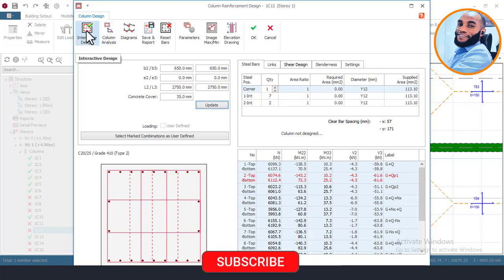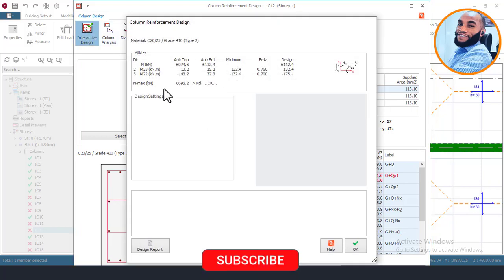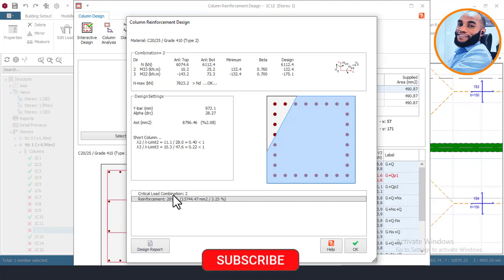And I'm now clicking on interactive design here, and I'll wait for the column to design again. Once you're able to see your column, if it's perfectly okay, you will not see any warning in here. What you will see is the reinforcement. So once you're able to see the size of the reinforcement, then you know that the column is okay and is good.